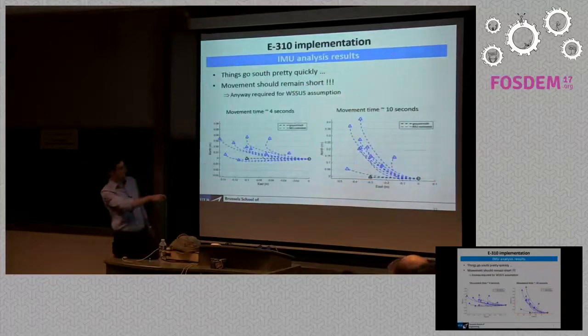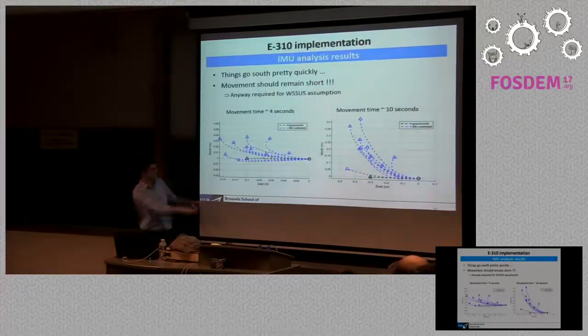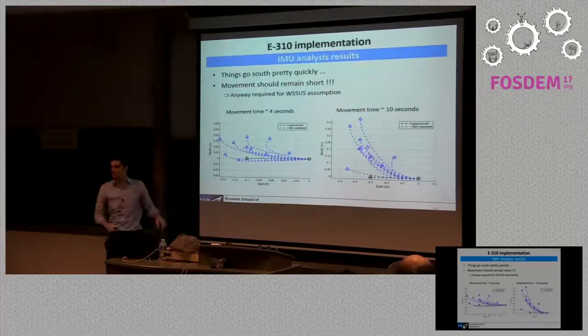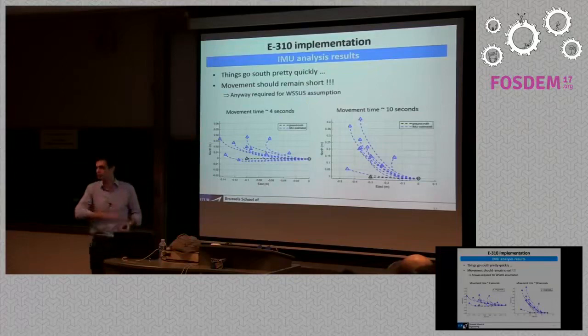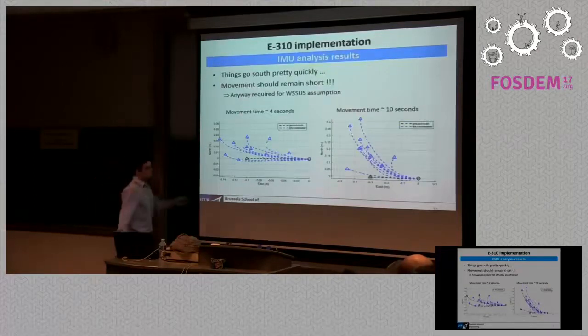So the black line here is the real movement that we generate, and the blue lines are the IMU estimated trajectories. So you can see that for a 10 centimeter movement here, we have around 5 centimeters of error at the end of the run, right? But it's not the 10 centimeters versus 5 that you need to think of, but we have 5 centimeters of error over a 4-second run, all right? So this is the way you should see it. Over 4 seconds, I can move my cell phone much more than just 10 centimeters, all right?